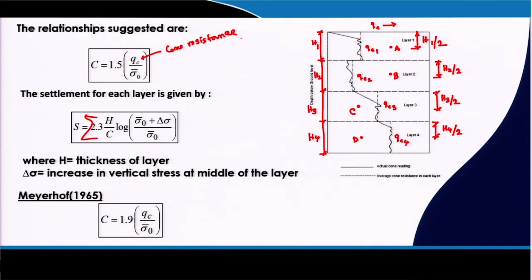So, I have discussed three field methods for calculating the settlement of granular soil: one is the plate load test, then the SPT and then the SCPT. In the next class I will discuss another two methods, the semi empirical methods and the influence line methods, and then I will solve one example problem to show you how we can calculate the settlement, and then we will go to the next part, our fourth topic, that will be beams on elastic foundation.